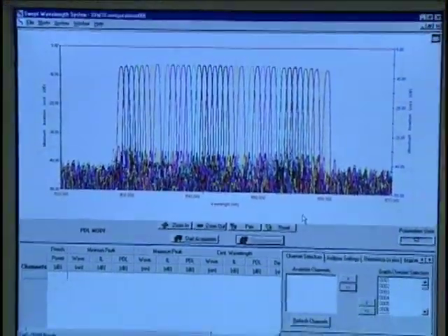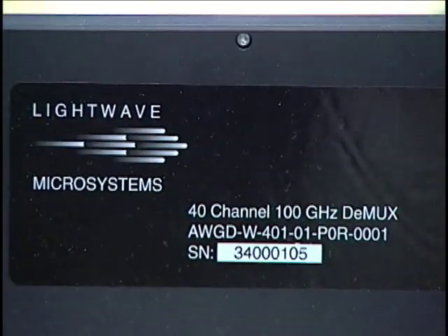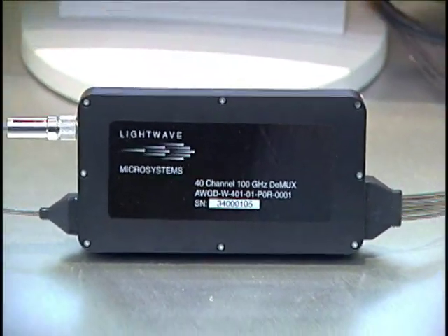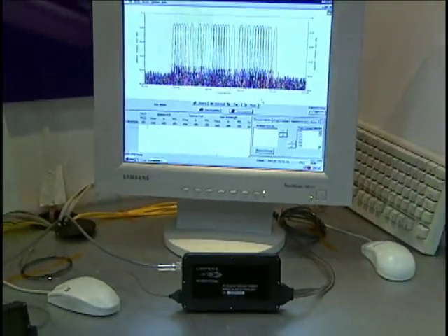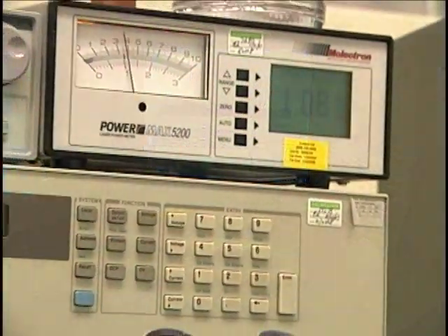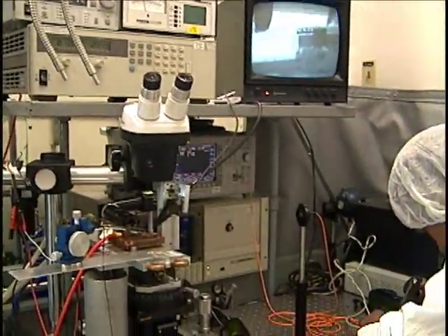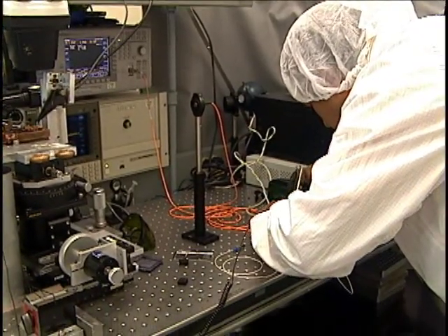As manufacturers began to produce lasers with tighter spectral widths, dense wavelength division multiplexing, known as DWDM, having optical spacings into the tenths of nanometers became a reality. This required optical filters to demultiplex these wavelengths. Another key requirement in DWDM systems was to prevent the optical drifting of the laser light sources. Wavelength lockers presented a solution to this problem.